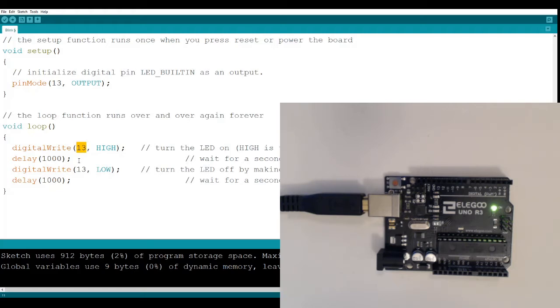Remember, the channels can be either in a 0 volts or a 5 volt state. This corresponds to low or high. High is the 5 volt state, so it's like flipping the light switch on. So we'll turn channel 13 on. That should light up the LED.